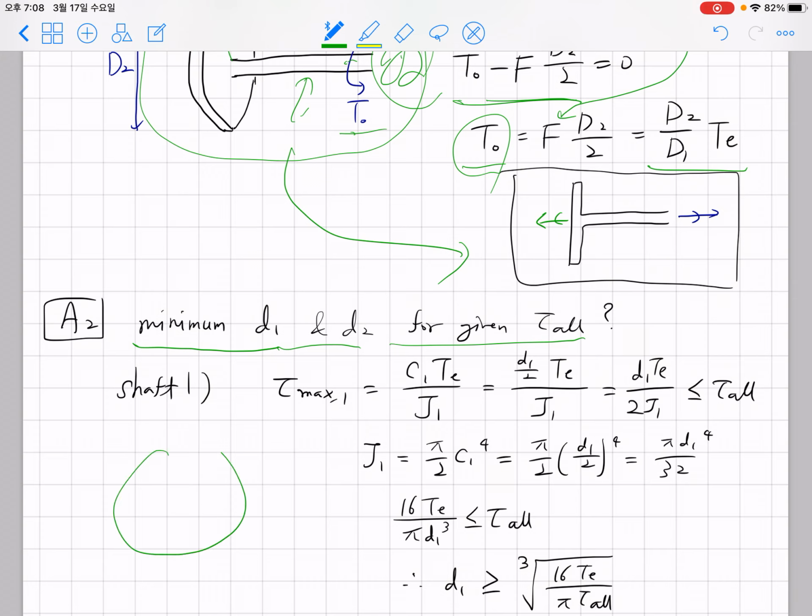So what you have to consider in a torsion loading problem is, in contrast to axial loading, where we had a constant and uniform normal stress over the entire cross section, we have different shear stress on different parts of the cross section. We're going to have higher shear stress as we go further from the center. Okay, so this maximum stress must be smaller than the allowable stress.